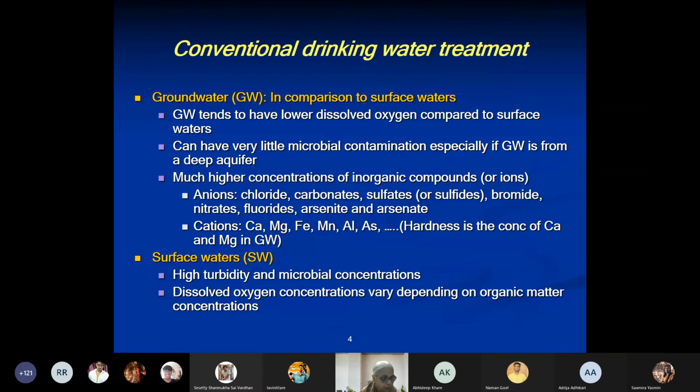I've already mentioned to you that soil is generally contaminated with fecal matter from all kinds of sources, birds, animals, humans, and so on. So all that material will naturally flow further down, but as the water carries it further down, it gets attenuated. So it basically becomes less and less because there's a longer distance for the water to travel and carry microbes with it, and the filtration through the subsurface is more and more obvious, right? So that is another advantage with groundwater. So it's good quality water. The only thing is dissolved oxygen is less.